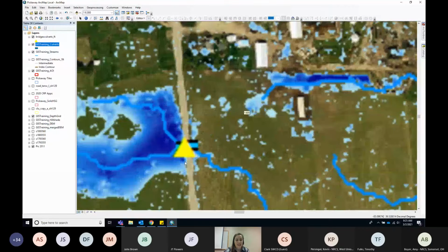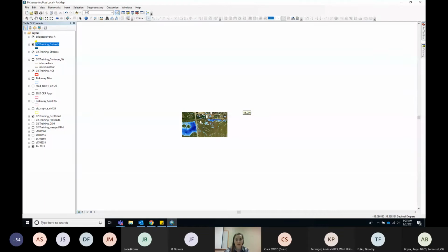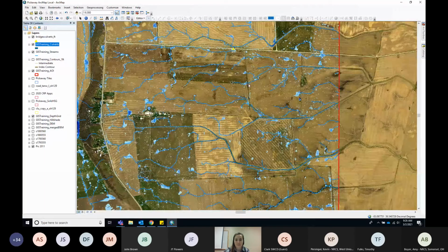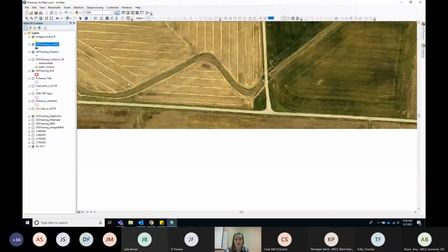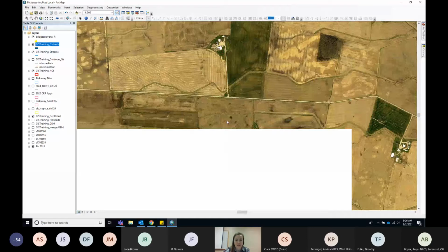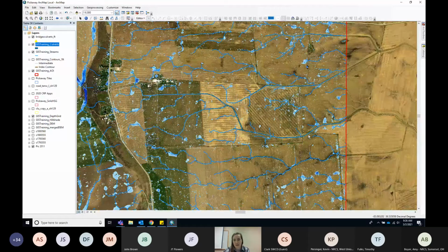But here you can see, because we drew on this culvert, this blue line now crosses this road. And then up here, let's go look at the other one. So now this crosses this lane. If you didn't remember to add that, it may still cross, but it might show it coming down here and then crossing back over. If it's not on your direct path, it's not the end of the world, but it's good to add those in because it can sometimes affect the one you're directly working on.